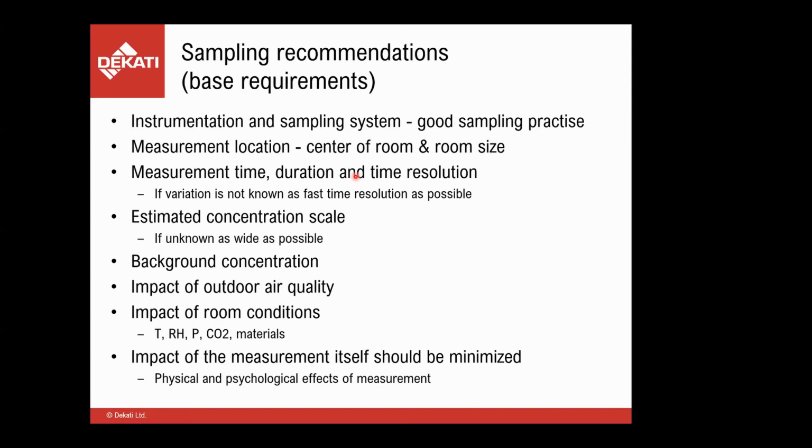You should take the background concentration into account. What we mean by background concentration is that when you have an indoor space or an indoor dwelling, as said, you should measure the background concentration so that all the potential aerosol sources should be turned off, and there should be no human activity in the room. Then you need to allow the concentration to settle, which may take hours, to get a sort of background concentration baseline for the indoor space.